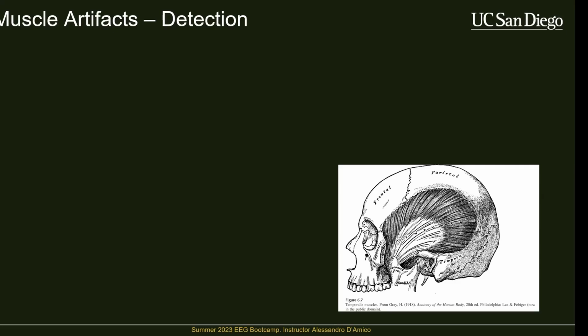Recently, a couple months ago, I was recording a subject with a professor, Andrea Chiba, and we just had one of her research assistants in the room. Hey, Shauna. And we weren't really paying attention to the subject's condition, but we noticed that all of the electrodes on her, I think it was her left side, so like T7 and the electrodes around there, were bursting with a lot of high frequency noise, but her right side electrodes were totally fine.